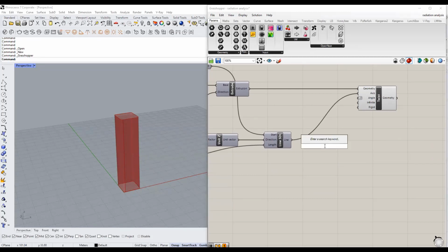I will just create a number slider by typing 90 ... 360. So instead of giving the number for the slider, I'm giving the lower and the upper limit. I'm giving minimum 90, maximum 360 using this format, 90 ... 360. Enter, connect it here. Twist happens for 90 degrees. I can just play around with this value and see how much twist I want. Let's just give a random number for now.